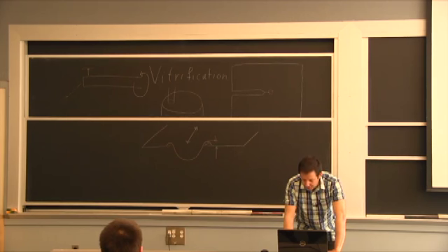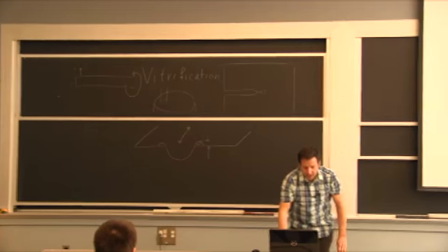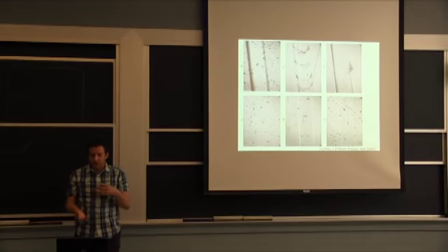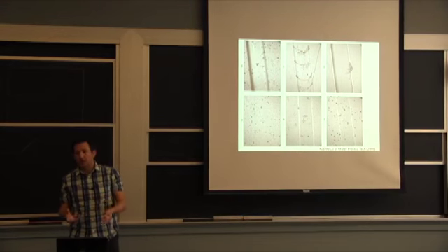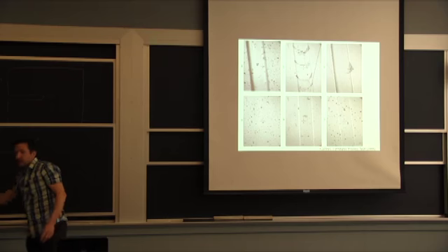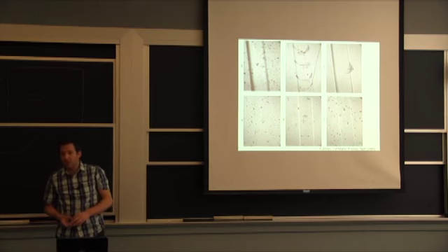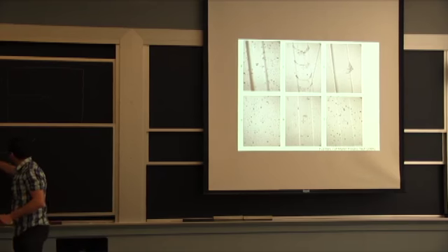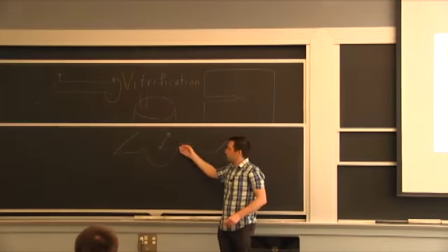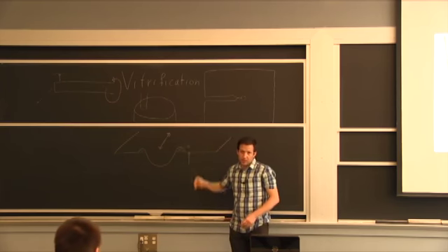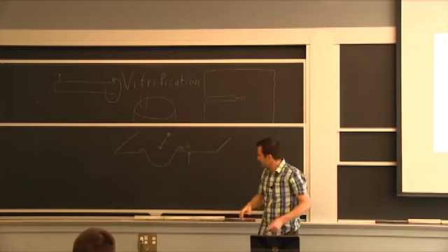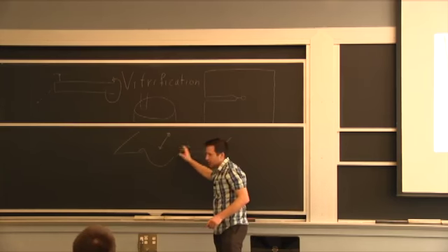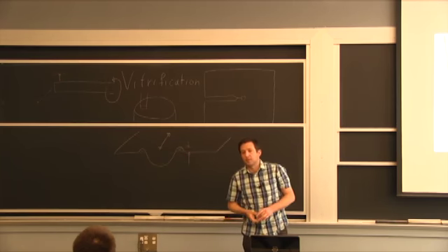But for applications of abrasion that we were talking about, you will have some hard particles in the sandstone. You'll have in any media some particle that will form essentially scratch type damage, a permanent deformation of the surface. So you have to design for losing thickness over time. And the way to reduce the loss of thickness is to minimize the amount of material that is extruding out of the surface, because in subsequent wear processes, when you have another abrasion particle that comes here, eventually you will remove the material.